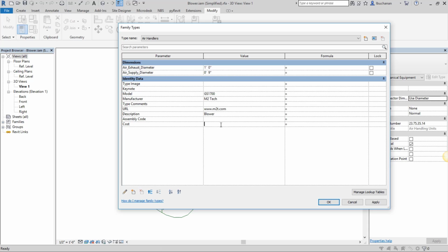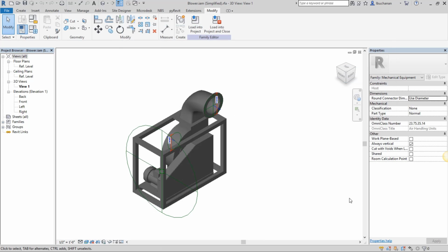And basically that information will then be translated to our Revit model, and we can actually schedule it as part of the project. So we can start getting cost values if we want to in our project. You can add in additional parameters like some of the spec information or operation manual information, and then that can also come into a project.